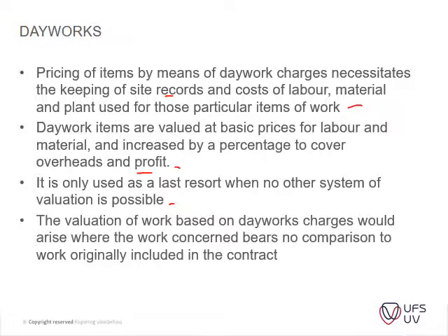The valuation of work based on the day works charges would arise where the work concerned bears no comparison to the work originally included in the contract. So in short, if you do not have rates or other items measured for those items, then it would be best to use day works, and only then will day works kick in.